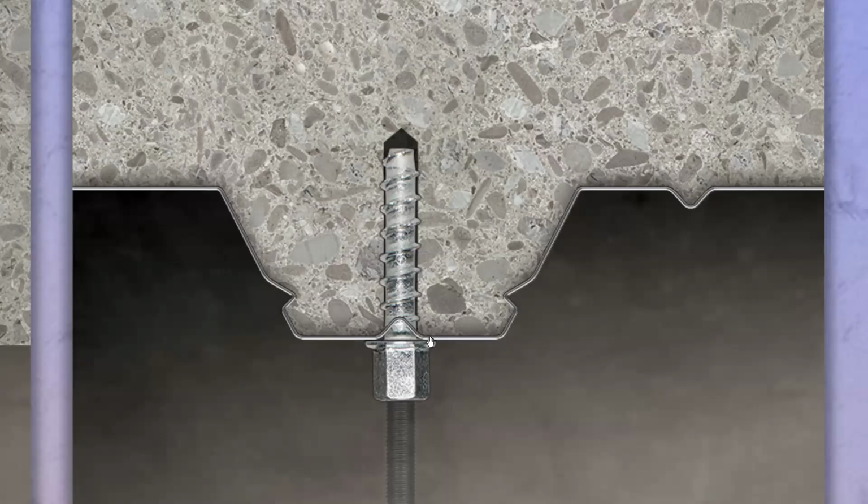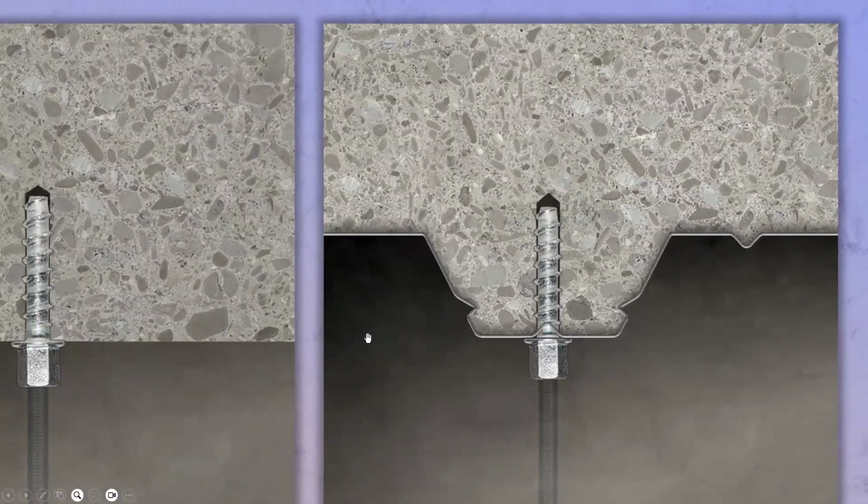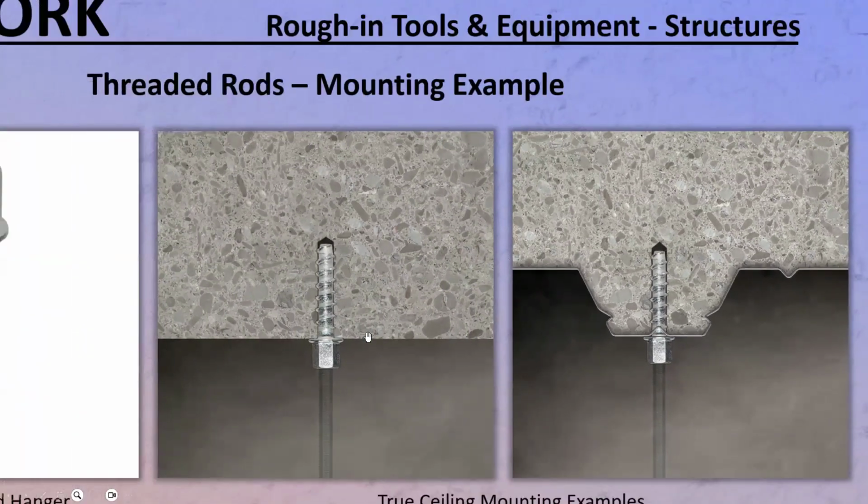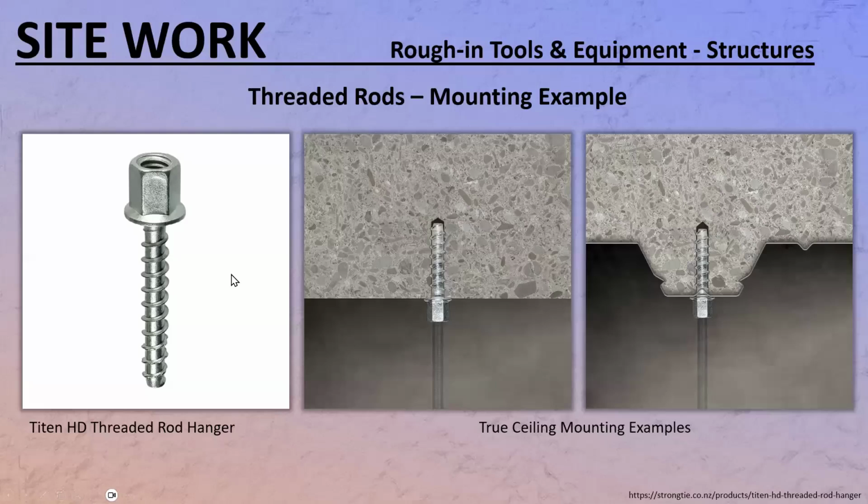First you have to drill through the steel, using a different type of drill bit, and once you drill through the steel, you also damage that drill bit because you're going to go a little bit into the concrete. You change the drill bit, and then you keep going. Some of those jobs, yes, they can be interesting. I'll tell you that.